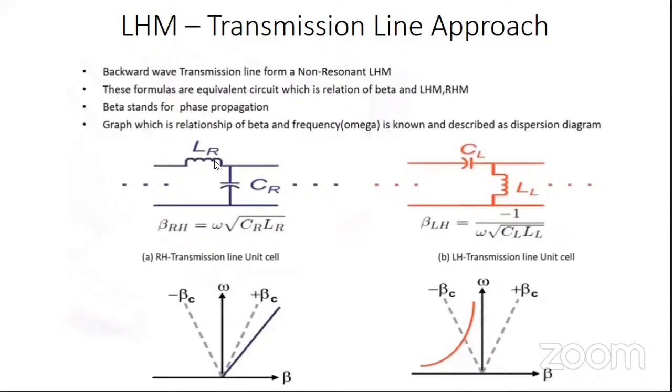Okay, so this has to be reversed. This is the normal structure which we usually encounter in our transmission line network mode analysis. We usually equate the entire circuit as the series inductance and shunt capacitance, whereas for the metamaterial approach, we have to reverse these two components. We have to get the properties of series capacitance and shunt inductance.